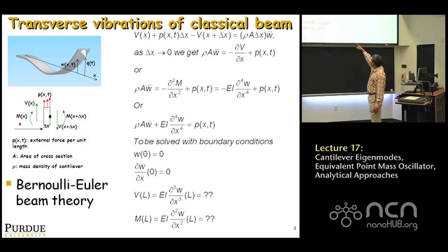What should really happen is this shear force should equal mass times acceleration of the tip. That's what you should get. The force at the end of the beam should equal mass times acceleration of the tip. So if you set it equal to 0, you're effectively saying the mass of the tip is basically 0. For the most part, that's not a bad assumption because the mass of the tip is usually 10%, maybe 5% that of the mass of the cantilever. Maybe you can neglect it, but we'll discuss today that often you can't neglect it, okay?